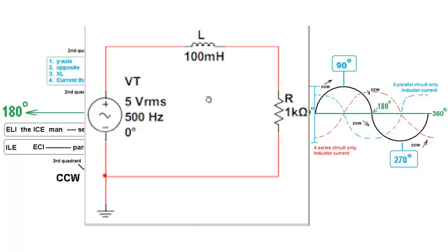The other thing one should keep in mind is what do these components have in common? In this particular case, they have current flow in common. The same current that's flowing through here is the same current that's flowing through here. What they have that's not in common are obviously their inductance, or the resistance, and the voltage drop across each one.